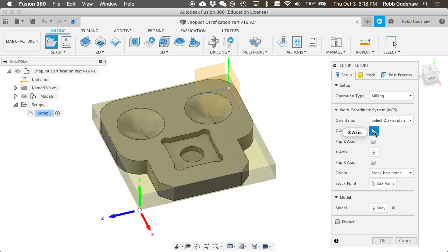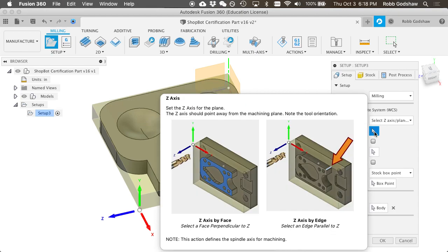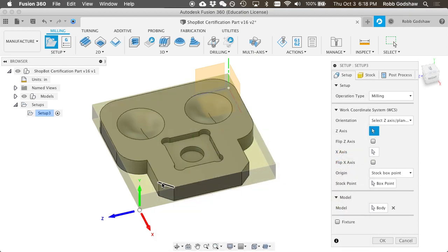It can do either. You can see in the preview that you can do a surface, or a line, or a surface perpendicular to that line. So I'm just going to click this line. And that's kind of better, but Z is pointing the wrong direction, so we can go ahead and click flip Z. And I want my X and Y to be both positive along the part, so I want the X to be flipped also. So I'm going to click flip X.